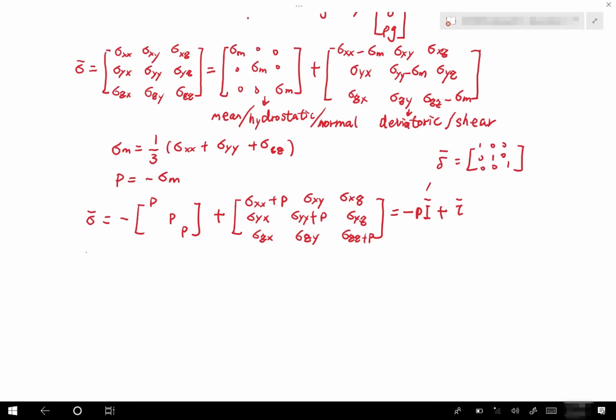That shearing stress is proportional to the velocity of the relative movement, right? And it is also proportional to the distance between the two plates. So it's proportional to V over distance. So that's like a gradient, right? This is how we observe it, and that's the beginning of deriving a formulation for the relationship between tau and v.